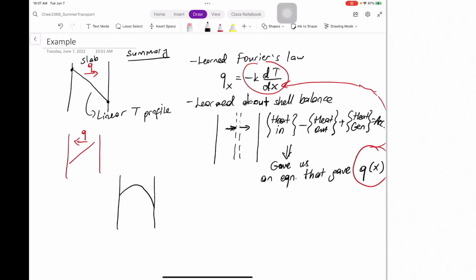In such a case, since the temperature is increasing on the left and decreasing on the right, the heat flux is to the left on the points on the left and to the right on the points here. So heat is flowing to the left in this region and flowing to the right in this region. So we are going to see such an example. It's nothing fancy, but you just have a look at how the temperature is changing. If it's increasing, you have the flux flowing towards the opposite side.